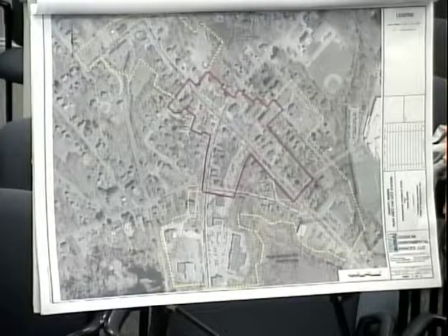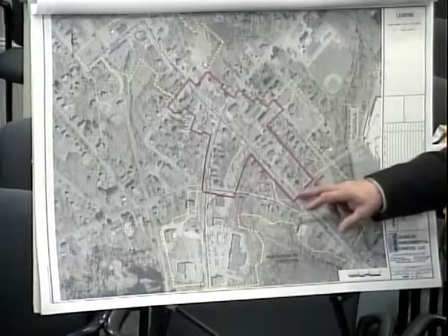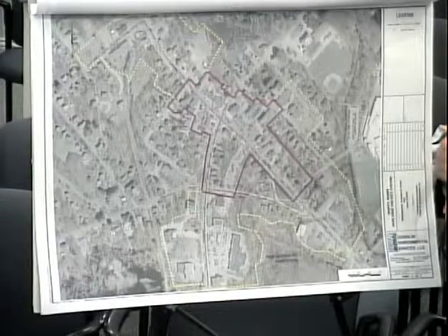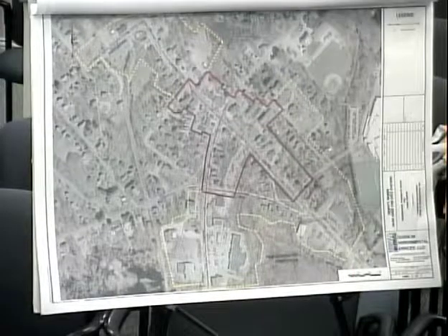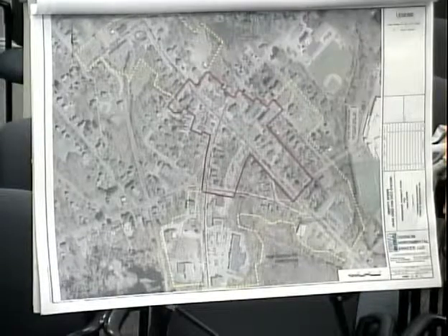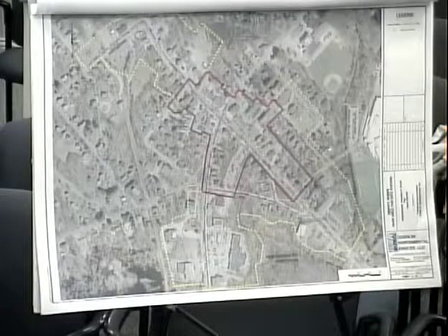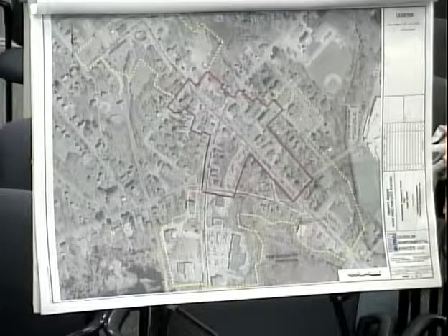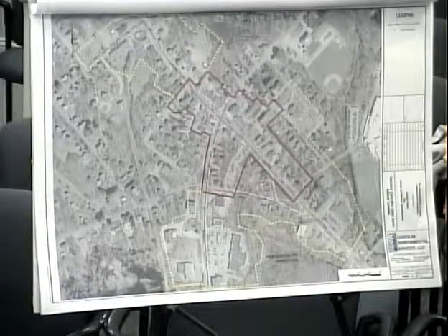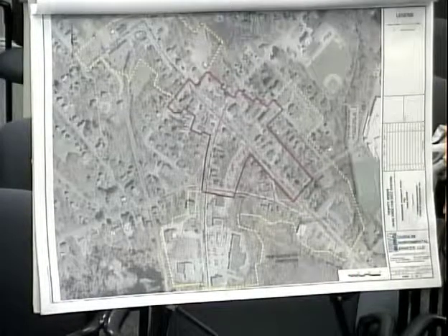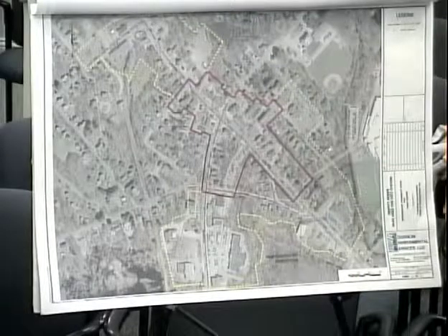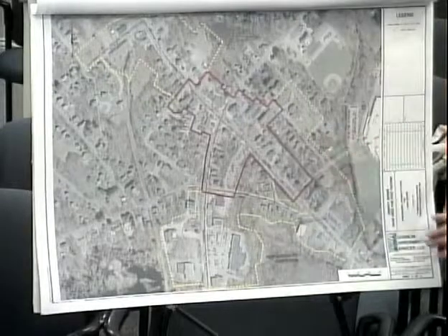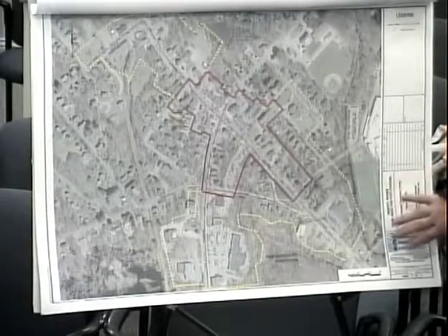So you don't really gain any advantage depth-wise with that system. You're still going to be down fairly deep. You are removing solids with the septic tank before it goes to the gravity system. So in theory, you could cut down the size of your pipe to maybe 6-inch or something like that. But typically, I wouldn't do that. You always want to have your system with a low flexibility, and if you're going to put in a 6-inch pipe, you might as well put in an 8-inch pipe. So there really isn't a lot of advantage in going with the STEG system, okay?